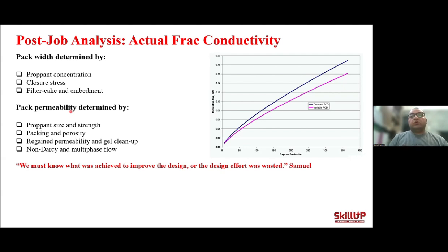Because if you have the same well and the same formation, and you pumped like 100,000 pounds of proppant, you will get a fold of increase of 2, for example. What if you pumped 200,000 pounds of proppant? You will get a fold of increase of 2 as well.